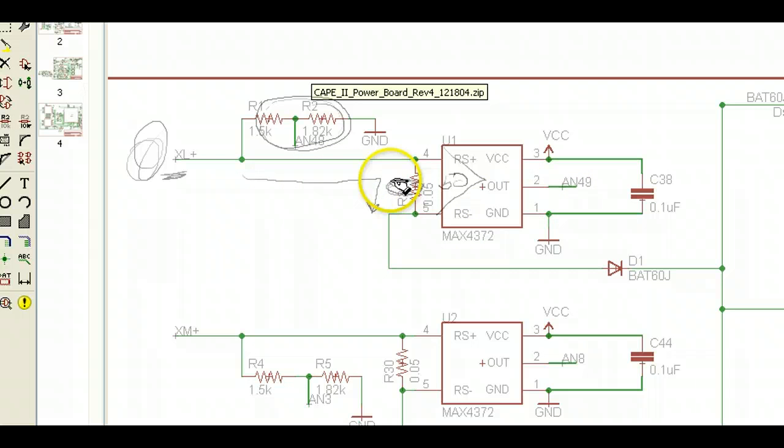So the power progresses through this small dropping resistor, and we show a diode here, but that's going to get removed and placed on the solar panel boards, and it goes to a bus. This bus is the always on bus, and that's one of the 4 main buses on this power system.